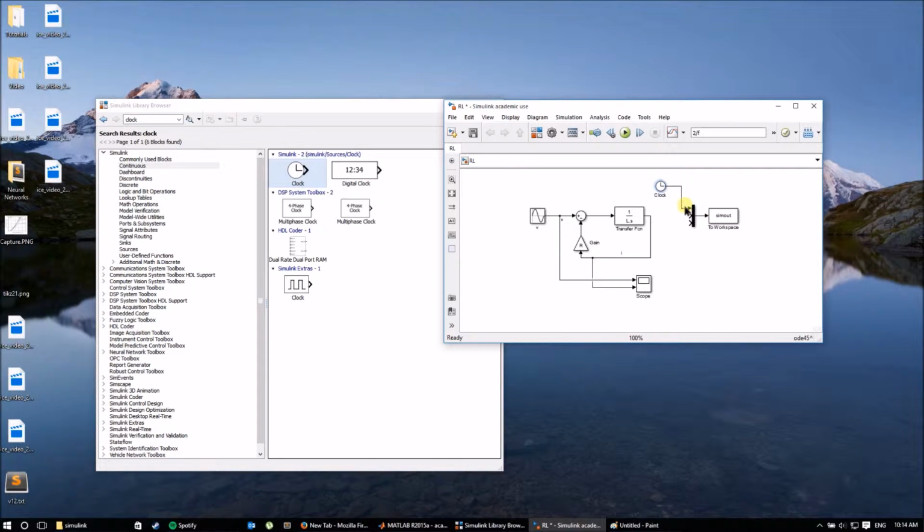So we put, for example, the clock as the first variable to save. This is again the same as PSpice when we said we have to open the out file and check which column is which. You can see it here visually. First variable to save is the time, because I put the clock block. Now I will save the voltage for the sake of it, so I'll just drag it here, and then I will save the current.